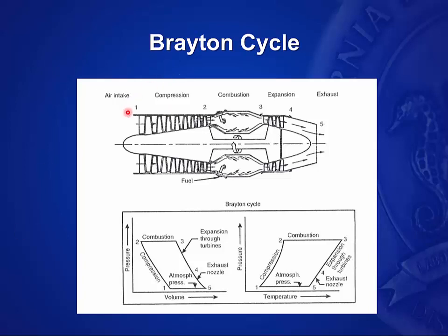In this, you have the air inlet, so it's flowing into the compressor section of the gas turbine. It is compressed over as many as 16 stages. And as you can see as it goes through, as the pressure goes up, the volume is decreasing. It flows out of the compressor section and into a divergence into this expanding combustion can, where fuel is mixed and combusted.